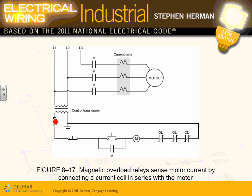Okay, here's the current coil. This is how it looks, guys. If this is a 10 amp motor and now we're pulling, say, 25 amps, this guy will pick up. When this guy picks up, it will open these contacts, right? If one of them picks up, it opens this contact. When you open this contact, you de-energize this coil, and up it goes. This coil will open these contacts. Any comments, guys? Any questions?